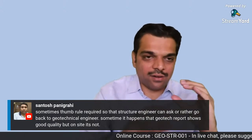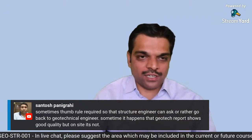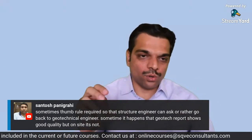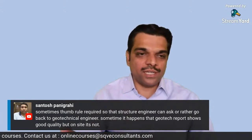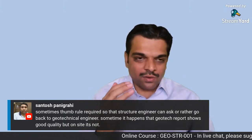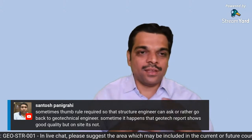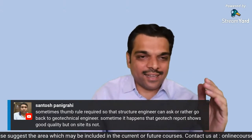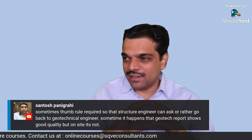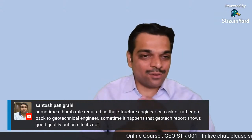See, let me tell you a very quick experience from a few projects. Whenever we are doing a soil exploration, we are not doing exploration for the entire site, we are just doing random boreholes, okay? And soil itself is a heterogeneous material, so there could be a large variation. In one project, on a pipe rack which had a maximum span of 10 to 15 meters, on one side the rock was at around 20-meter depth, and on the other side the rock was encountered at a depth of around 3 to 4 meters, which was not envisaged in the soil investigation report.